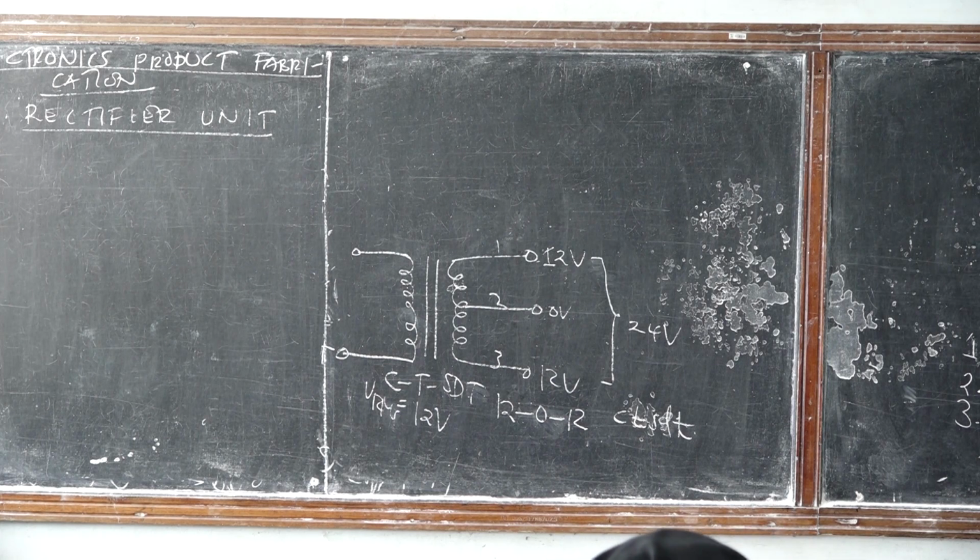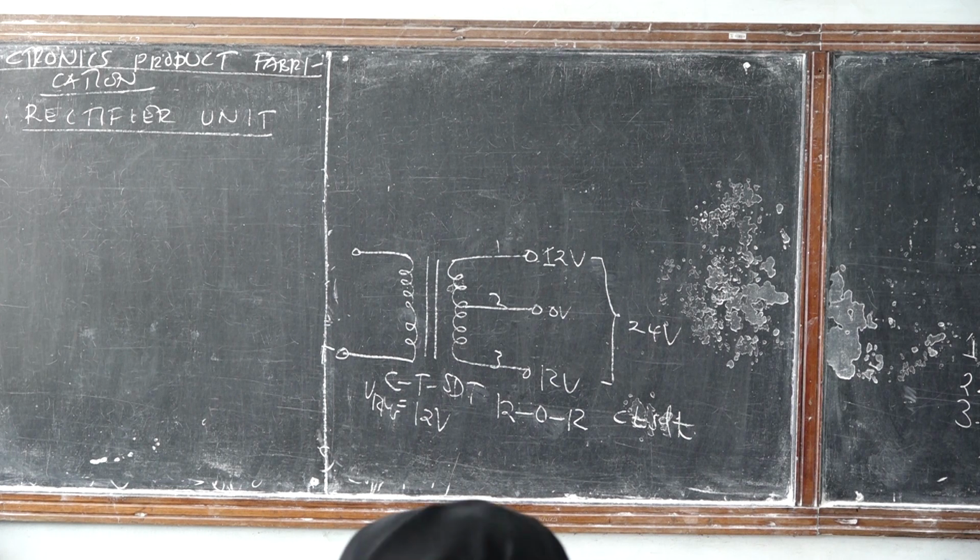So the transformer matters in your design of a linear power supply. The challenge we have, especially in your institution, is that students are not careful in the choice of the transformer. Especially if the system you are going to power draws a large amount of current, so large amounts of power, you can find that you do all of your designing, and then when you test it, the power supply is not working at all.